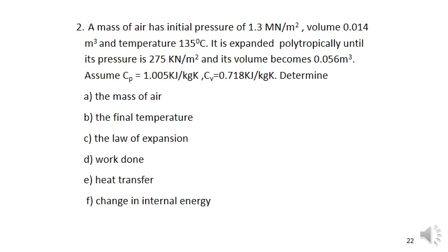So here they say it is expanded polytropically, but they didn't give the polytropic index value. So first we have to calculate that index value by using the formula n is equal to log(P1 by P2) divided by log(V2 by V1). So by using that relation we have to calculate the polytropic index value.